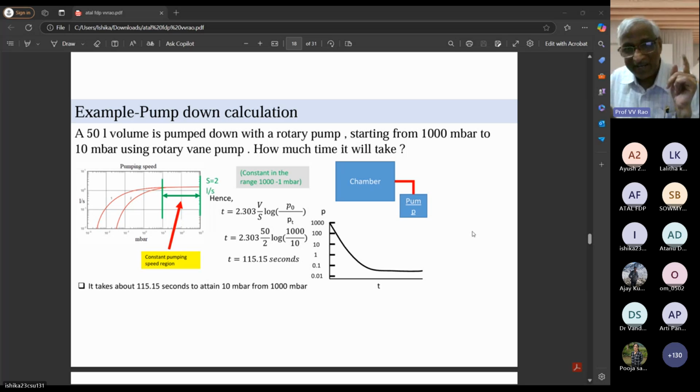This takes 10 minutes, 99.9%. That will take 20 hours. And this pump is 20,000, that pump is 20 lakhs. If you don't want high vacuum, the chambers can be rough. The chambers are very simple, iron or stainless steel. But in high vacuum, you need gold gaskets. So the cost of the chamber goes down 100 times, the cost of the pumps goes up 100 times, and the time also goes up 100 times. And component cost also goes up. All that to remove only 0.1%.